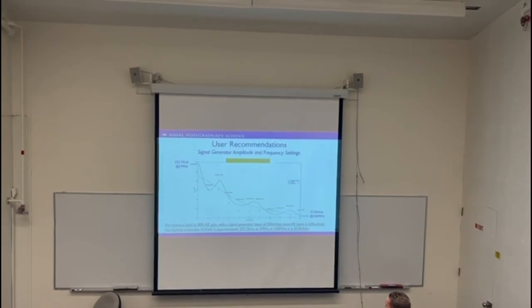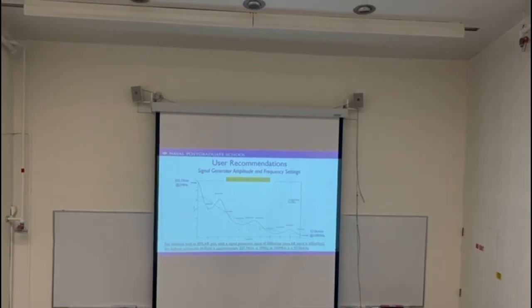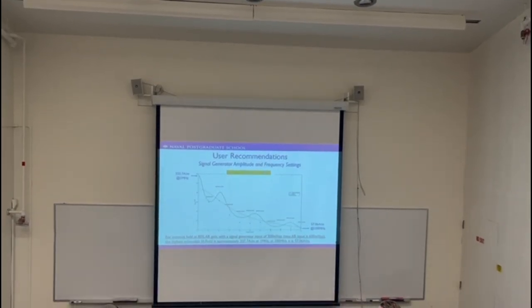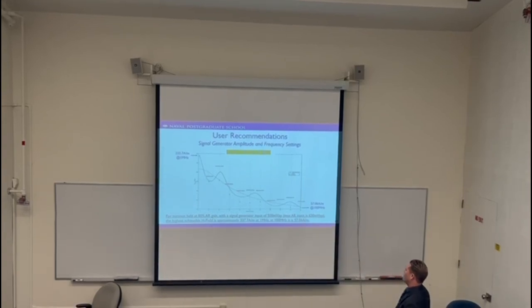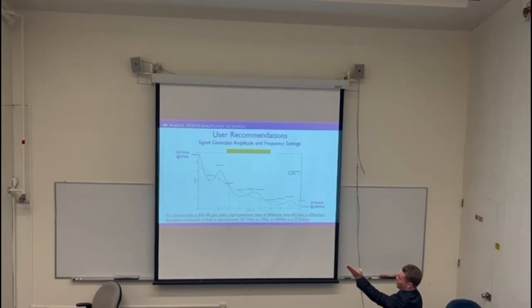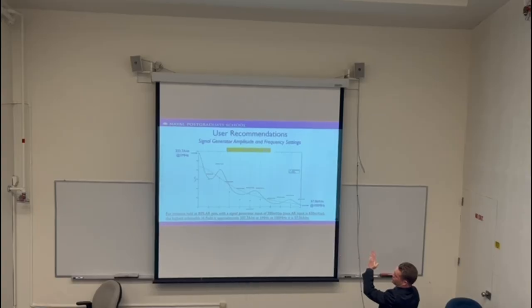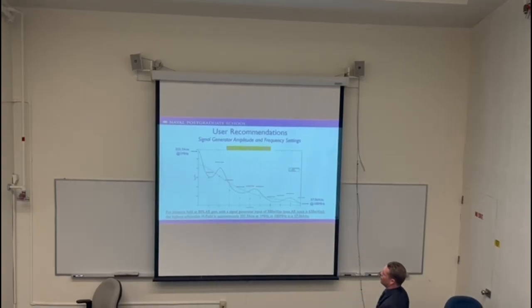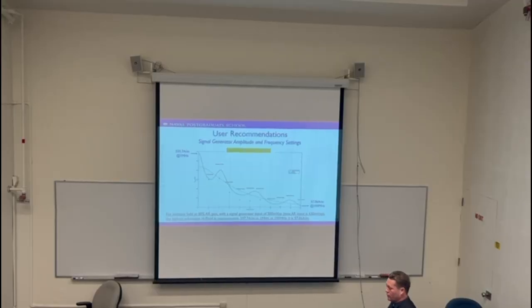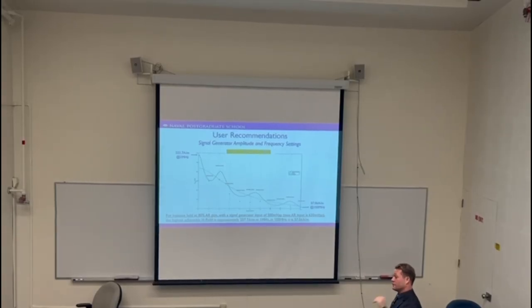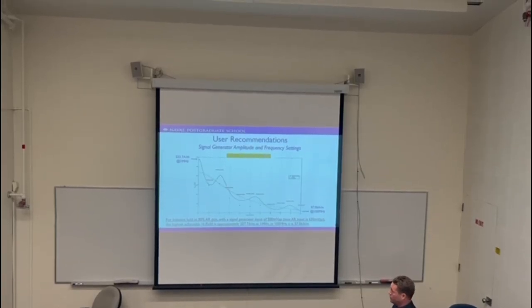And you can see here again, very nice overlap with the measure to model here. All the way up to 337 at 1 megahertz, and 100 megahertz is 57. Notice what a drastic slope that is, though, versus frequency, right? That's quite a negative slope. So in using this from a user standpoint, you've got to realize, okay, when I'm really low frequency, I'm going to get quite a lot higher H field than I am if I'm going higher frequency. It's going to drop off drastically. So that'll come into play.